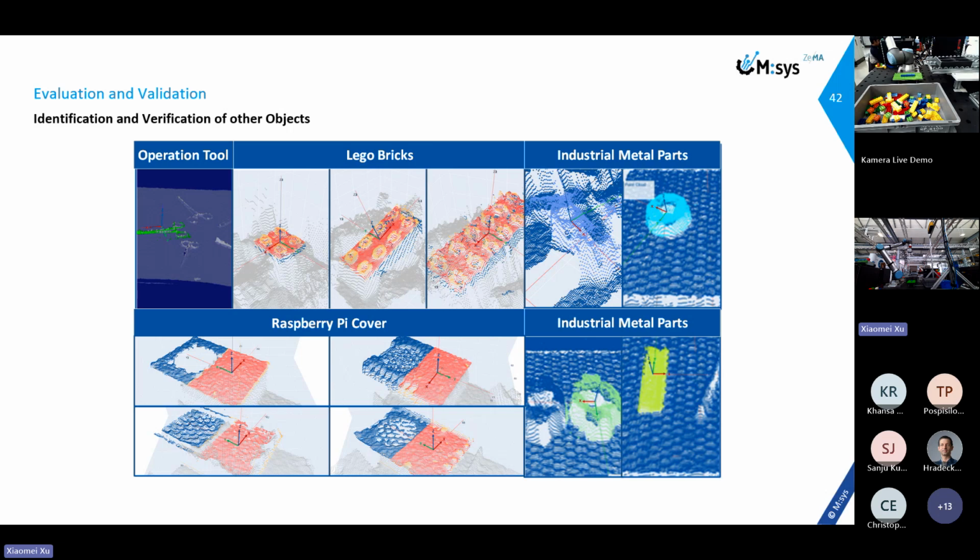Strict conditions reduce the error, but drastically cut detectable items. The commercial tool dropped from a high to few detections. Hence the metal parts lose more than 50% of the point cloud data under poor lighting and reflection. Micrometer resolution cameras are needed for precision tools, but higher resolution shrinks the working space, a trait requiring project-specific optimization.